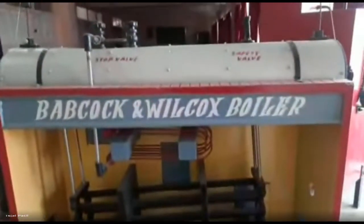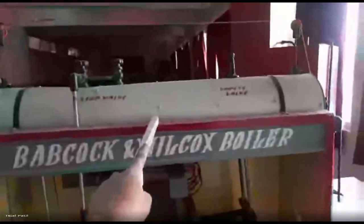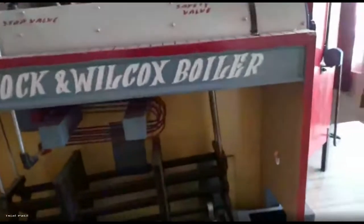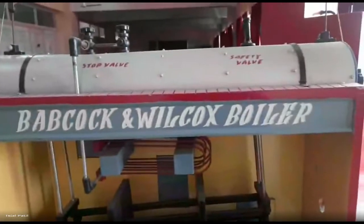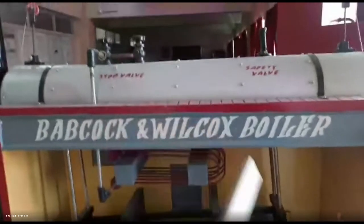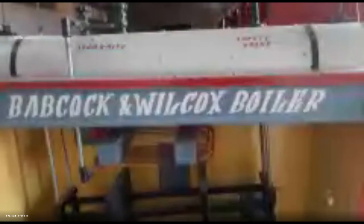Let's say in the boiler the requirement of steam has been reduced, but the steam inside the shell is continuously accumulating. The pressure will increase, and if it goes beyond the design limit, this safety valve will open and release some amount of steam into the atmosphere, so that your boiler will be safe.